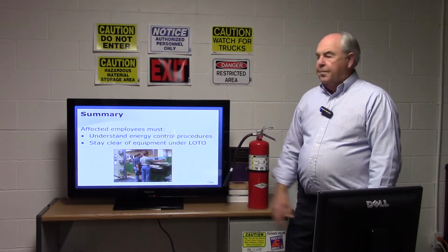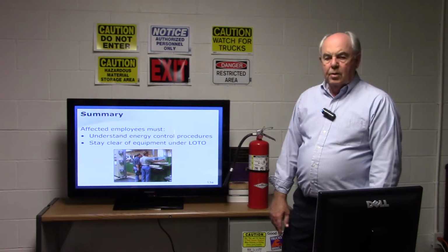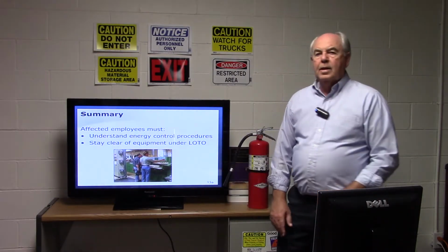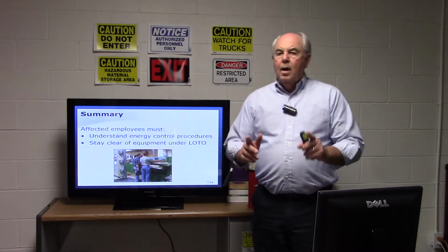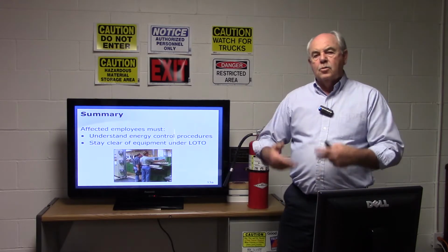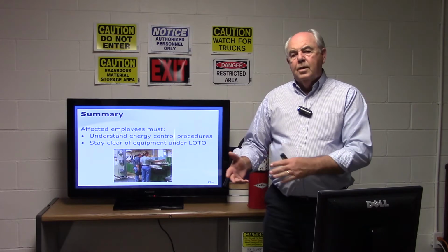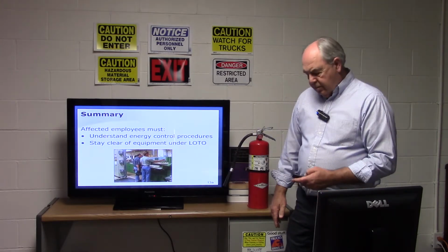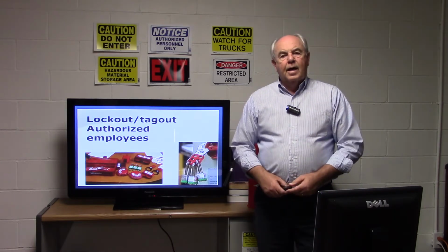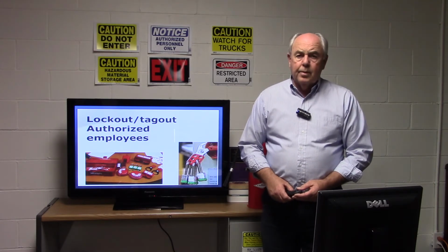So, quick summary. Affected employees must understand the energy control program procedures. That's what we're doing now. Stay clear of the equipment while it's under lockout tagout. Remember, only the authorized employees are allowed to conduct lockout tagout and actually use the locks and tags and enter into the point of operation to make some kind of repair or adjustment or maybe even maintenance or cleaning. So that's Lockout Tagout in a nutshell, and it's a really good program. It's a very important program for your